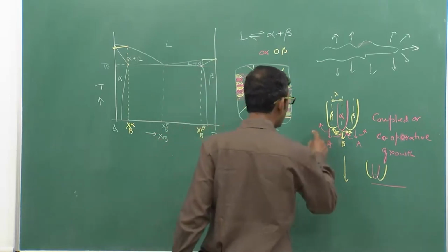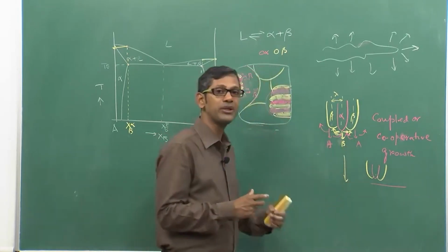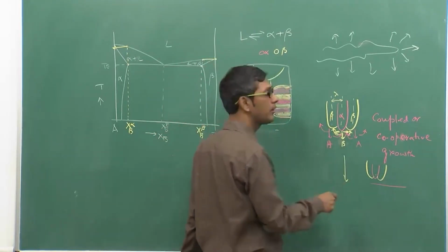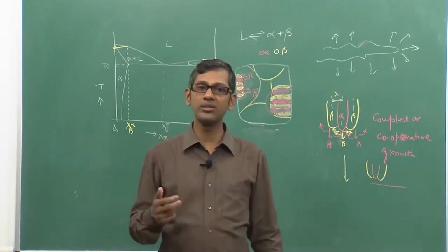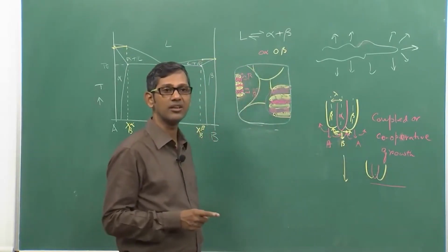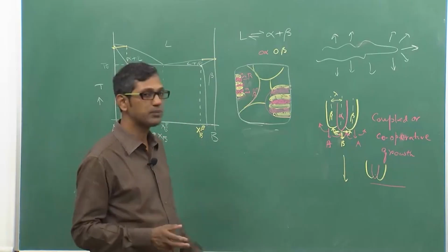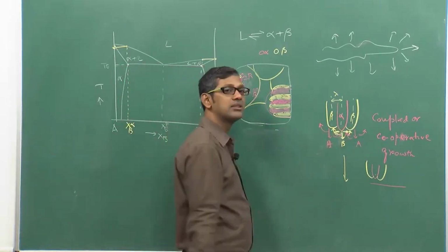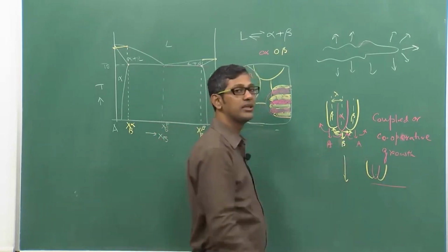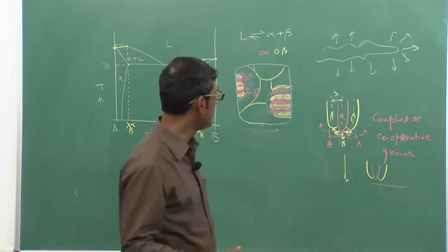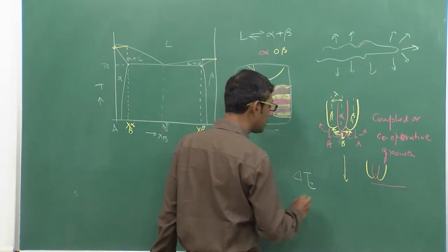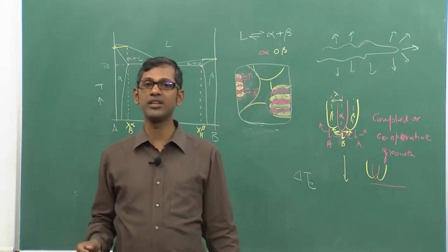If these atoms are not able to diffuse easily, the growth of this eutectic front into the liquid will be slowed down. So the growth rate will depend distinctly on how fast these atoms are transported via diffusion across the interface, not perpendicular to the interface but parallel to the interface, remember. So we need to calculate the undercooling required to diffuse or transport these atoms.